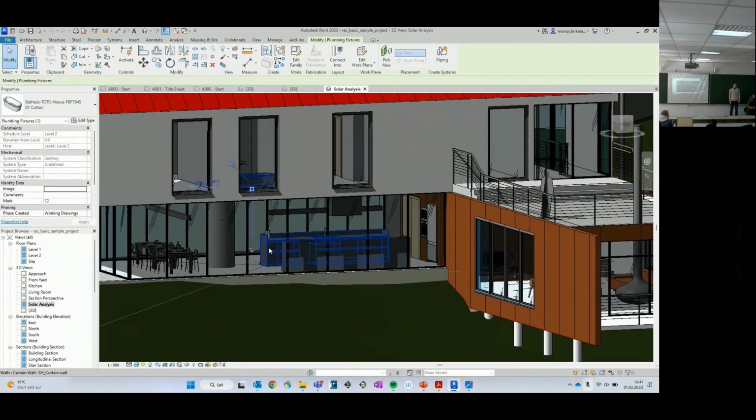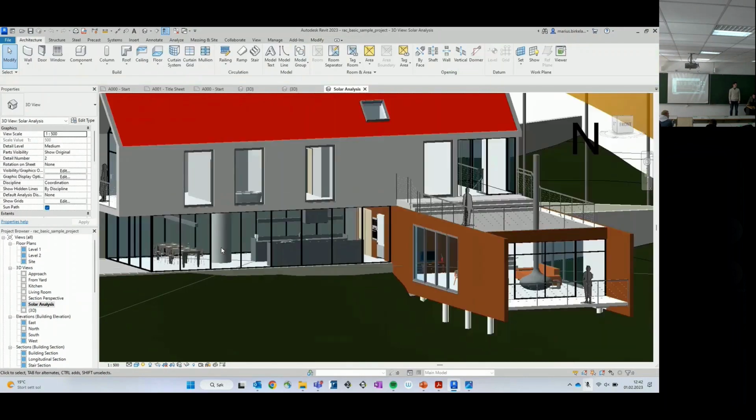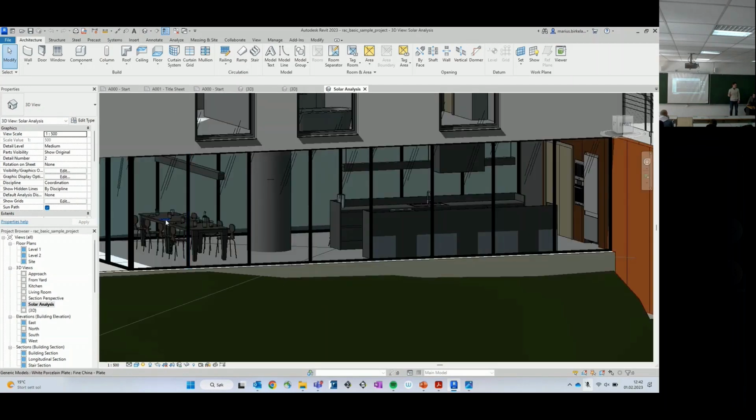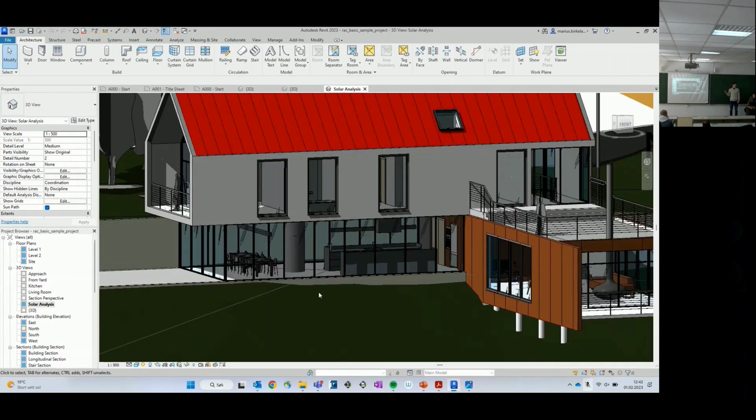Do we find Tekla easier for doing this work? I haven't personally tried Tekla for reinforcement, but from what I've heard from former colleagues, when you learn how to use Tekla, I would say it's about as good, and maybe even a bit better, because one issue with Revit is the way to schedule and mark the reinforcement. That's a bit tricky.